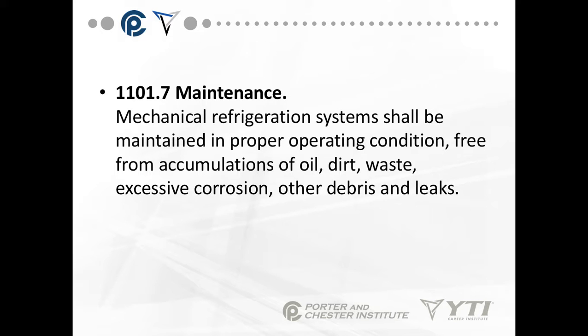1101.7 says that mechanical refrigeration systems have to be maintained in proper operating condition, free from accumulations of oil, dirt, waste, excessive corrosion, other debris, and leaks. So once the equipment is installed, it's up to the owner of the equipment to make sure that they continue to follow the codes with regard to maintenance.